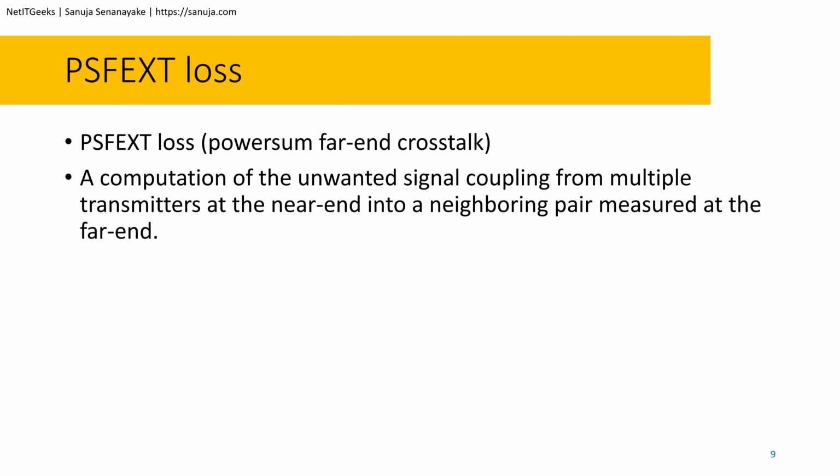High operating frequencies. Remember, every cable has a rated frequency, but if you're operating at a very high frequency, even outside of that range, especially as operating frequencies increase, for example 10BASE-T, the effects of crosstalk become more pronounced, making PSFEXT loss a more significant concern. Another one is lossy materials. While it is generally believed that lossy materials can help, it can also create attenuation for PSFEXT loss.